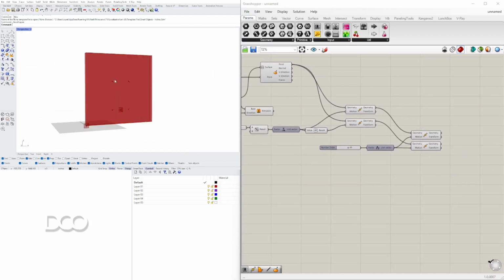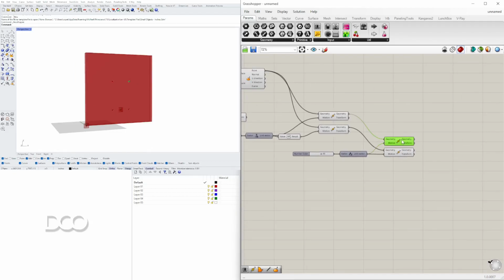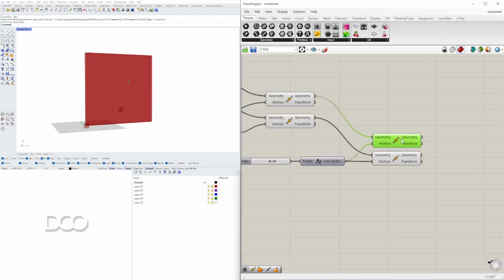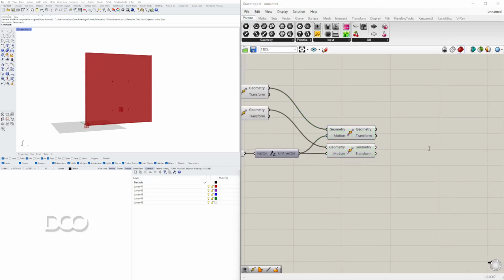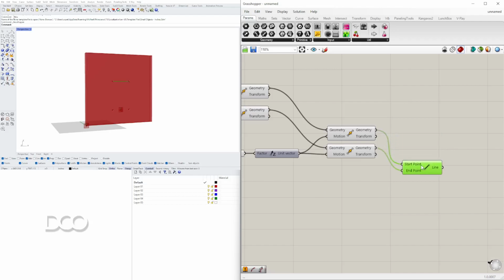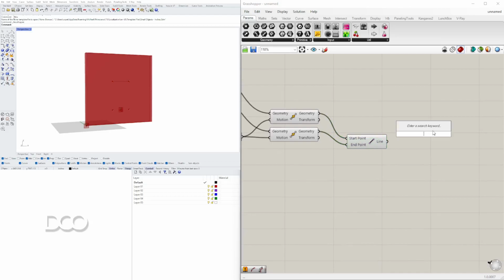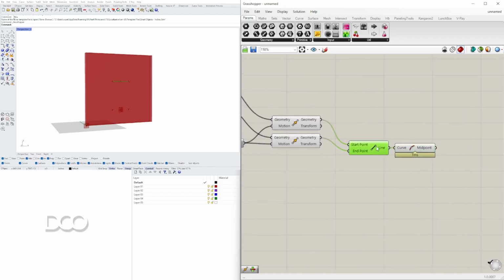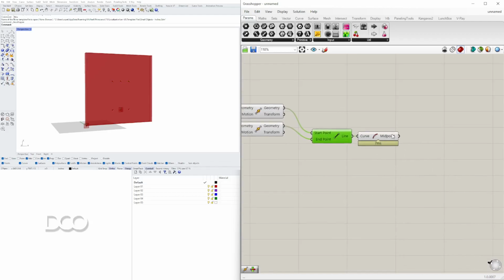Now what we need to do is create the arc here. There are different arcs that we can create. So let's start with the most basic one. The one that I would use would be between these 2 points, we're going to create a line. And in that line, we're going to extract the midpoint. We'll disable the preview on that line.